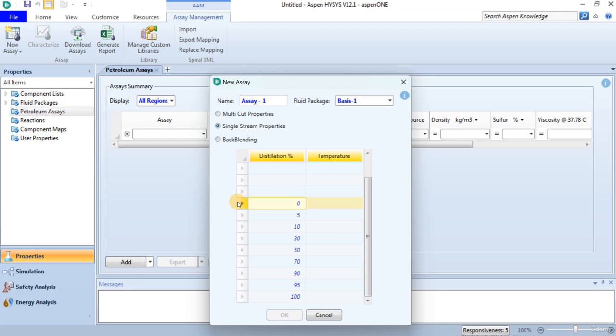In addition to the light ends, the oil assay will also include a volume-based distillation data curve, API gravity, and average sulfur content. Separate analysis of the gas product from the test separator is also available. This gas analysis will be defined when you enter the simulation environment. This gas material stream will be recombined with the material stream representing the oil assay to represent the composite hydrocarbon mixture.